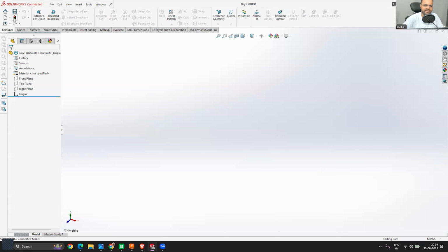But remember this icon that you can see, like a traffic light signal with the red and green bulbs attached to it. This tool is known as rebuild. Always remember this, rebuild. You can note it down in your diary that to use this tool, you can also use the keyboard shortcut Ctrl+B. If you use the Ctrl+B keyboard shortcut, you can run this tool called rebuild, right?